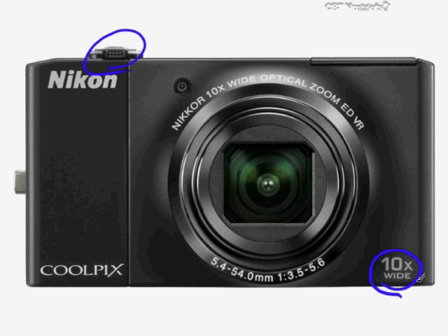Well, very often, that's kind of a fake resolution. What really happens there is, rather than moving the lens elements inside of the camera to zoom in and out, it will zoom to the maximum that it can with the lens elements, and then it will actually just crop the pixels in camera. So even though you might get 30x, you're getting a lot fewer pixels in the resultant image. So it's kind of a fake zoom is what I call it. Really just cropping in camera.